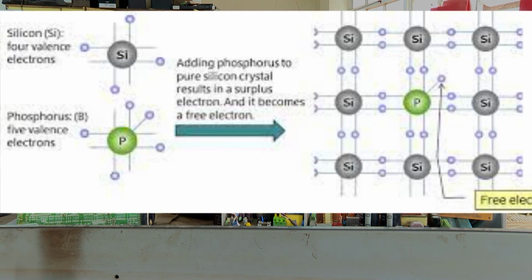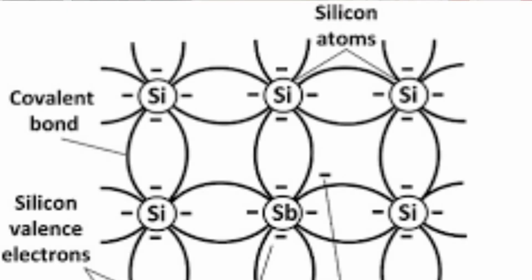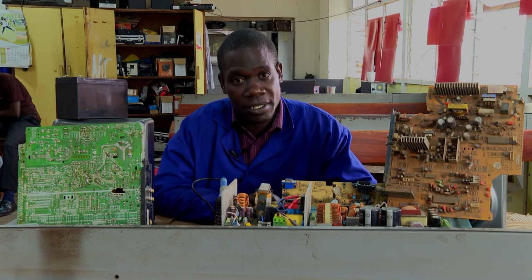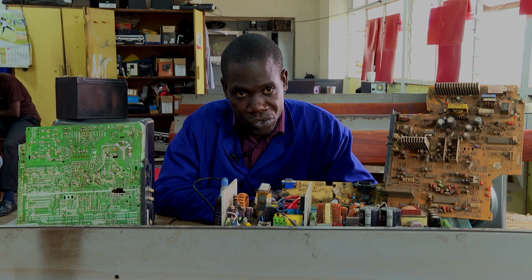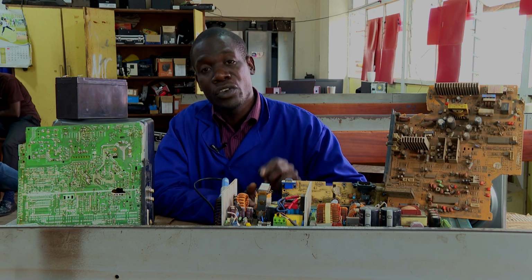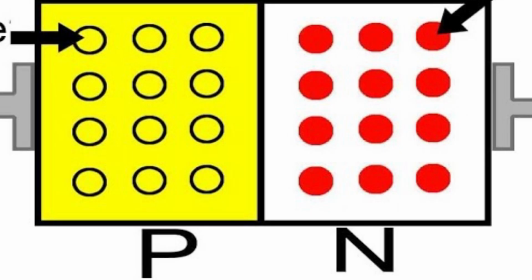But for a semiconductor to work well, we need to add in some materials. Which materials am I talking of? These semiconductors are in most cases made out of silicon. For silicon to be activated, you need to add some materials. For example, for the N-type we use phosphorus, so you dope in phosphorus, and for the P-type we always use aluminum, so they dope in aluminum.